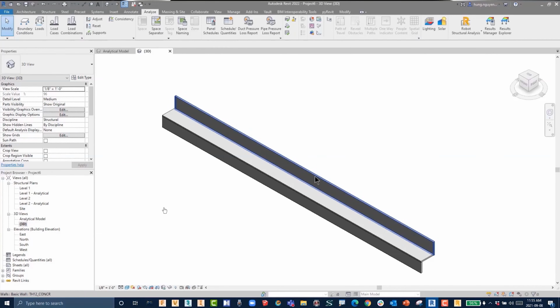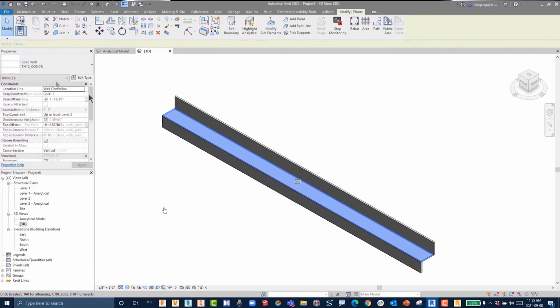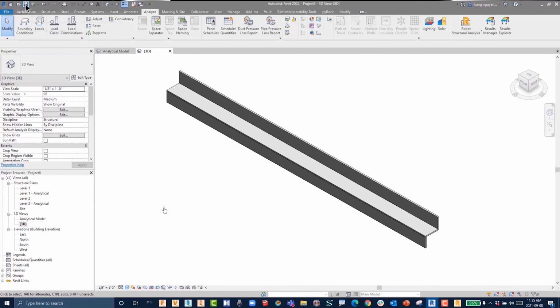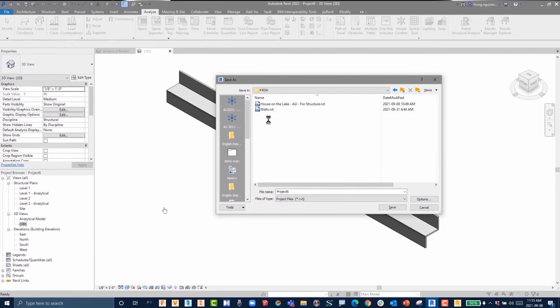You see now it turned that into a 12 inches concrete that is original set and override in RSA. So now it's about time for me to save that result onto ACC for Lina to do the copy, and she may need to replace the wall with the 12 inches wall instead of 8 inches or 6 inches wall that she originally set it up in this architectural model.